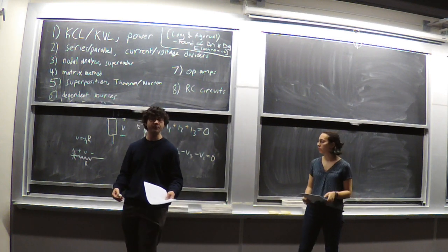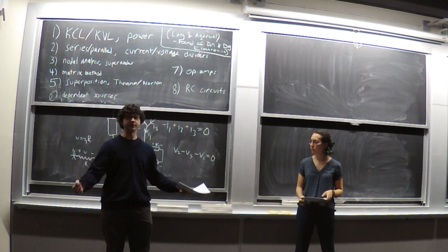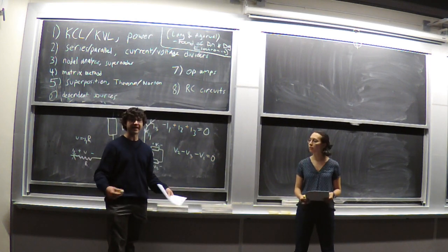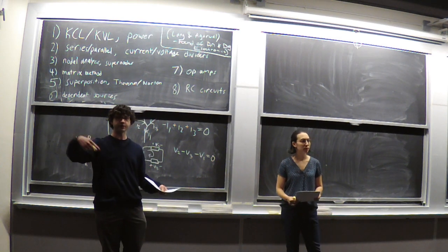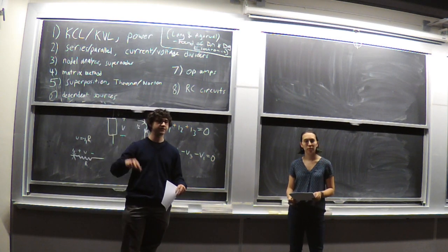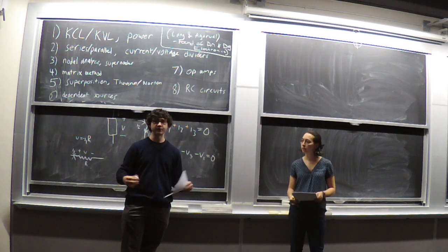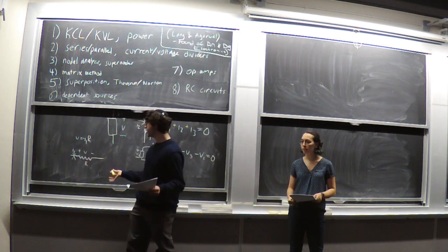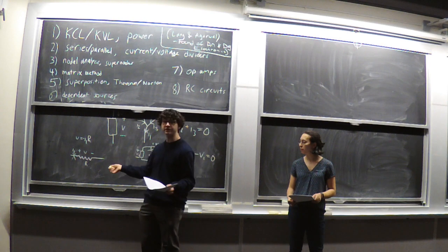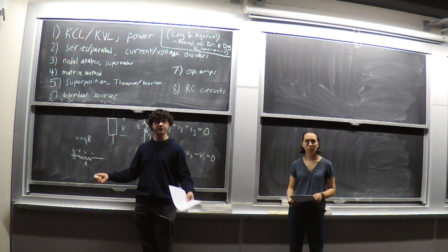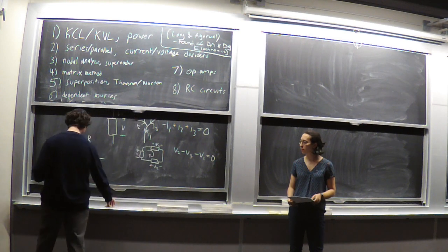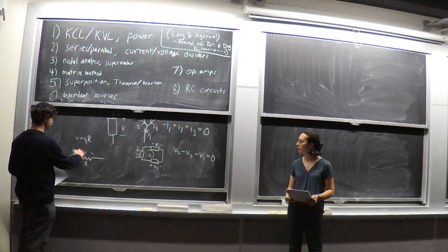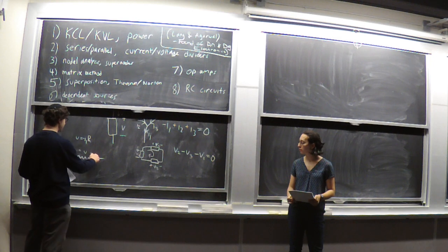Sometimes if you're given a problem, like an independent voltage source, it has the positive and the negative already defined because it's telling you which side has the greater voltage by whatever amount is listed. But if you're just given a resistor and there's no polarity already given to you, you can define either side as the plus or the minus. And it makes sense because if we were to define the voltage in the opposite direction, then we would get another minus sign, right?